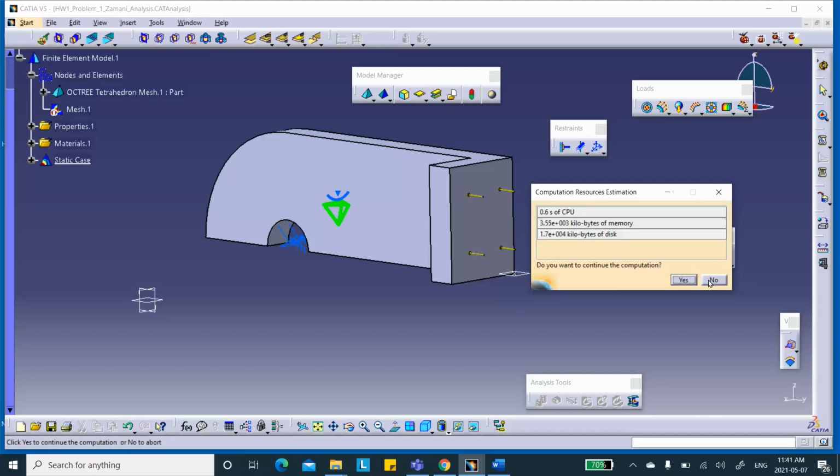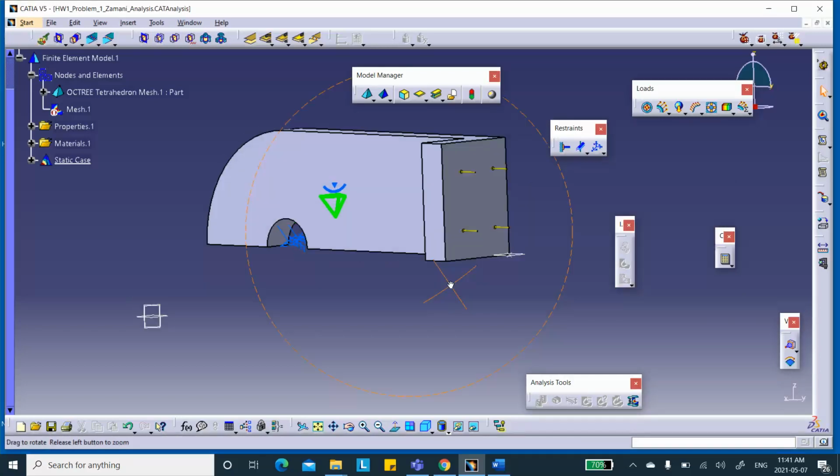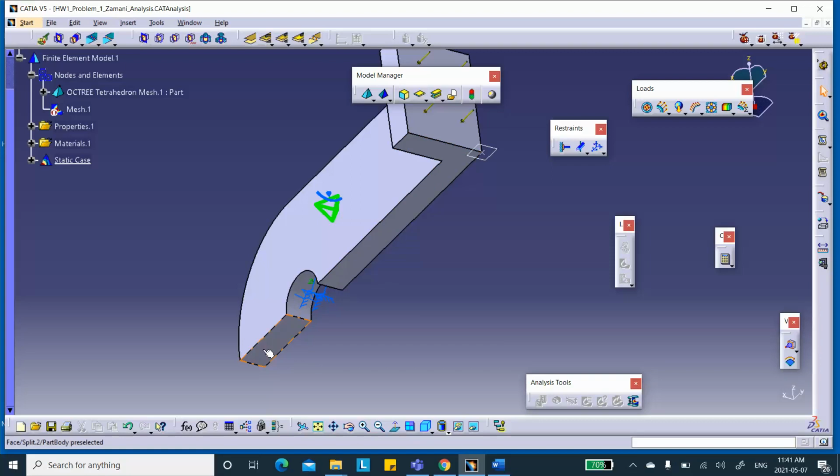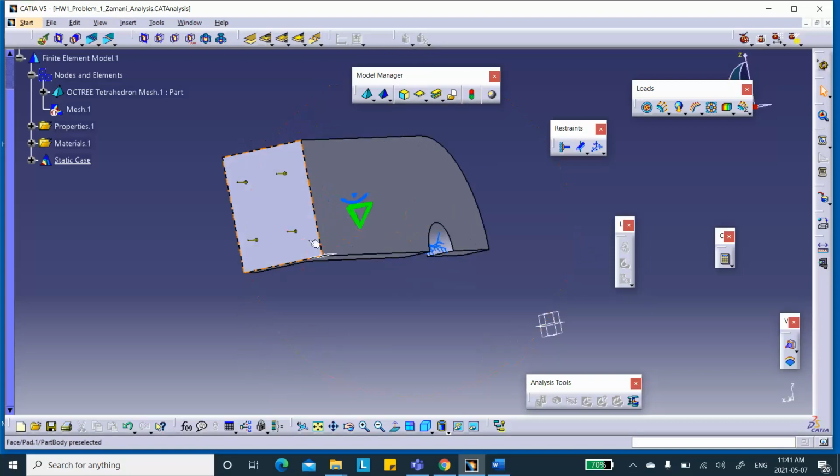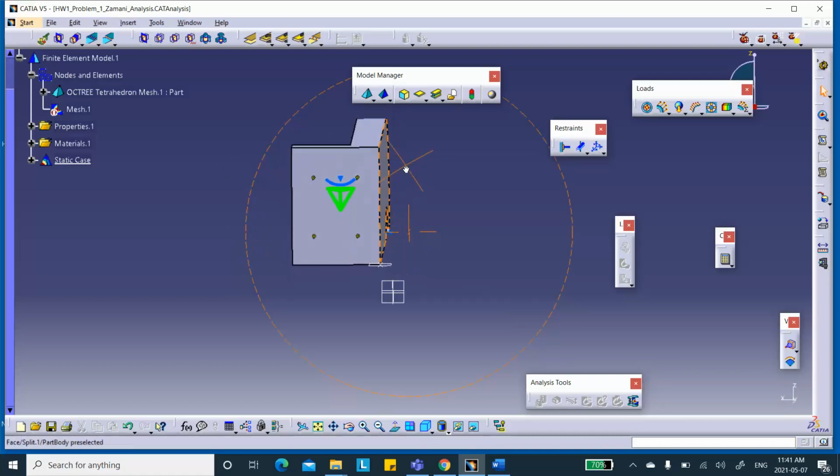Something that I forgot. Bad, bad, bad. No. When you make cuts, these surfaces that you create, you have to put surface slider on them because they're plane symmetry. Plane symmetry means that if I looked at it like this, a point in that plane will not go sideways to the left or to the right, it stays there.